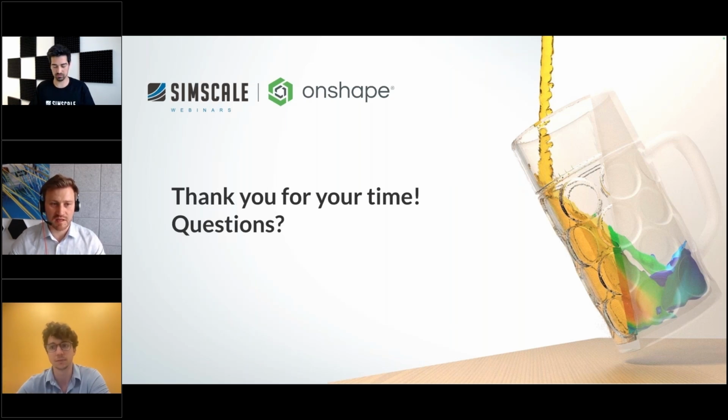Exactly, thanks. And also, if you want to get geeky about CAD kernels, SimScale and Onshape actually work really nicely together because they both have a parasolid CAD kernel. So there's great compatibility. You never see a situation where you bring something in from Onshape to SimScale and you have parts intersecting that shouldn't be intersecting, or unwanted sheet bodies, etc. There's excellent compatibility between the two tools.